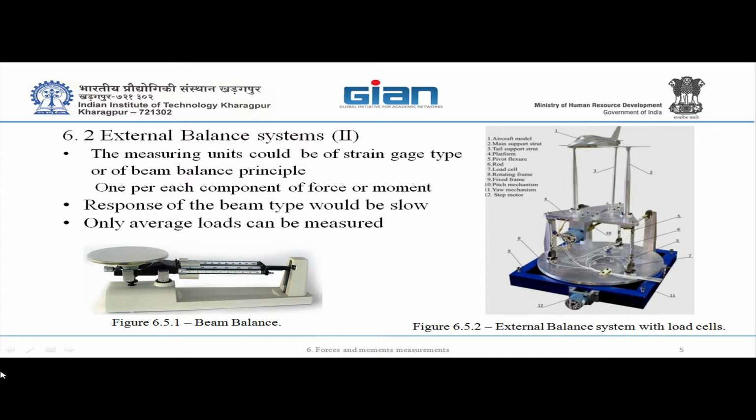The balance moment center, the BMC of the balance, could be in the aircraft also. Imagine it's a virtual point. The aircraft is supported at 3 points, three struts. That one is only schematic. You can support it with any number from 1 to 3, and no need for another one. Where it is supported, won't it disturb the flow? The wing is supported, so locally the flow may get disturbed.